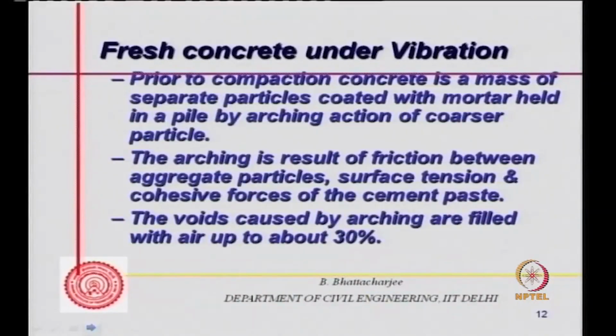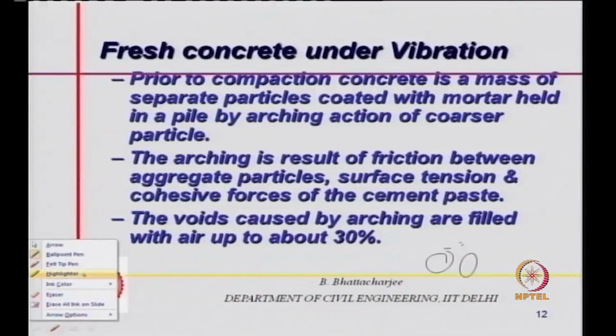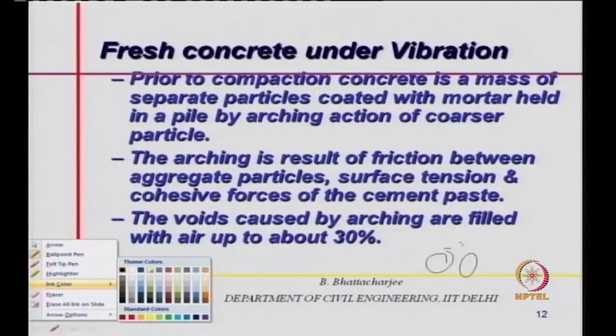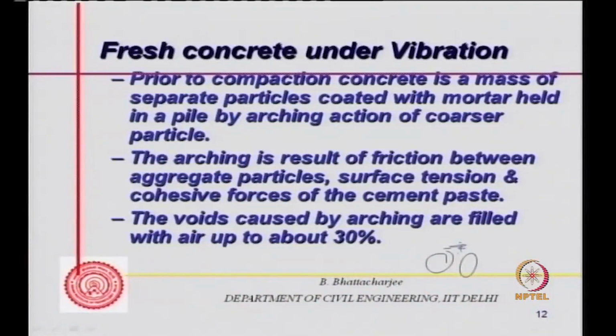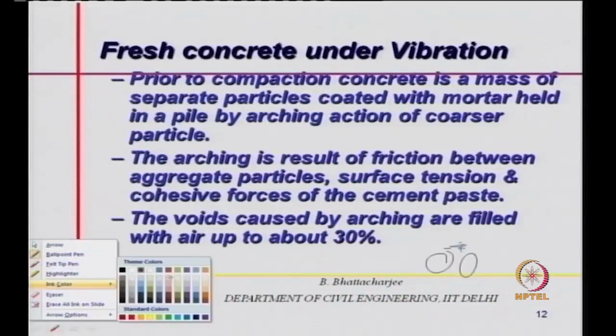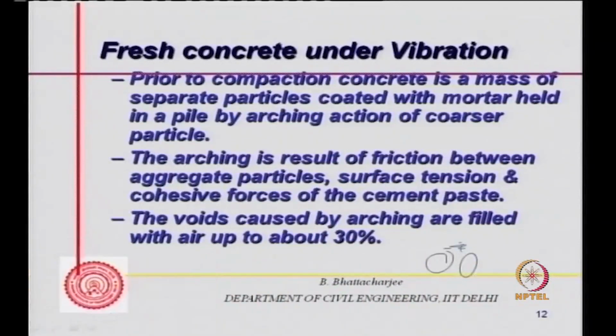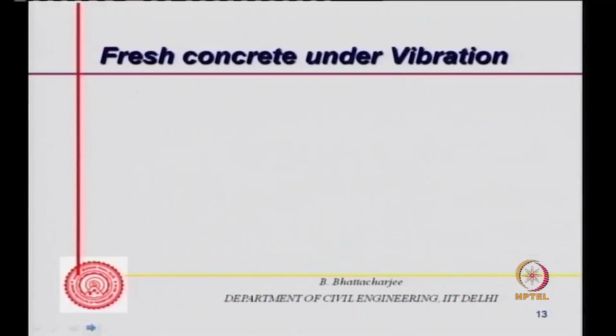So this arching actually results in a void of air of about 30%, because the particles are something like this, and there is mortar, as I said. But there will be an air gap in between, some amount of air gap. This air gap is about 30%, somewhere in between this particulate system, and you have to drive this air out. So that is the idea of vibration.